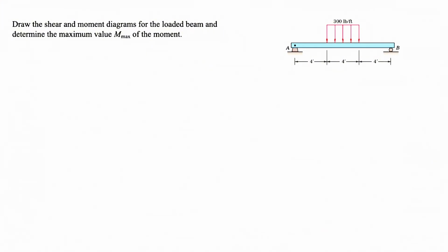Before we start going through the diagrams, we're going to start with finding the unknowns that we have at point A and B. Because we have a symmetrical beam in here, let's just consider the two forces that we need to consider for a pin, which is what we have at point A, and at point B we only have one roller. So since we are neglecting the effect of friction in the X direction, we only have a normal force, or By.